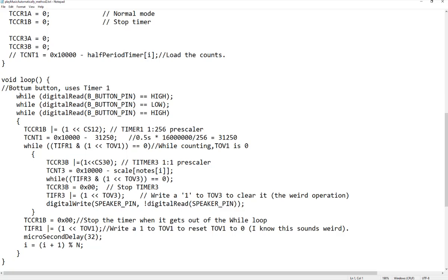So it's going to be a nested while loop. You need to know how to use the nested while loop to get this implemented. First, to detect the push activity, right? This one will hold it there when it's high. Whenever it gets into the loop function, it will stay here forever if you don't push it, because the semicolon will end it. There's no curly bracket to include any activities in there. So it's basically while it is high, because that's the active-zero button, right?